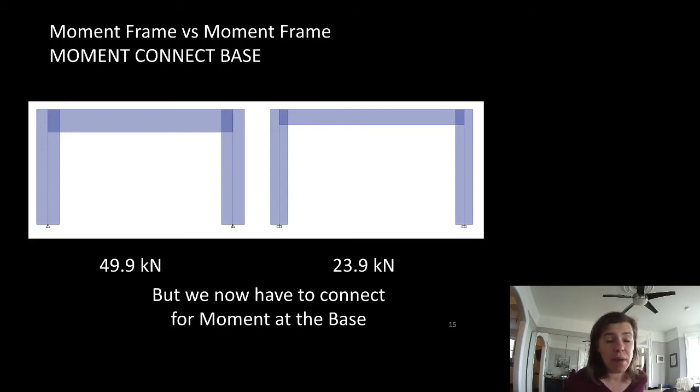If that's into foundations, we've got bigger foundations now. Maybe there's something else there and it's not a problem, but we have to be savvy and smart and think about where that load is going. Maybe we have a big, massive concrete wall here. If so, this might be no problem to achieve. Maybe we have delicate little sonotubes here. If so, this is not the way to go.